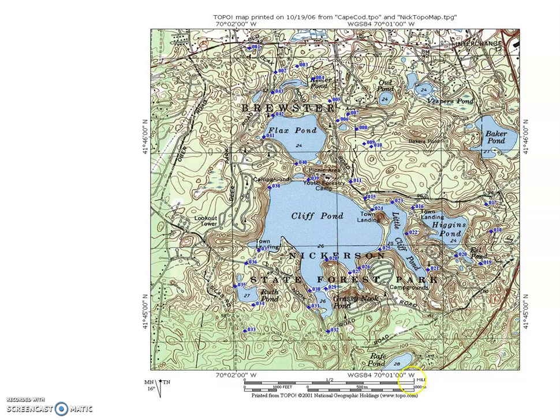So you'll notice that there are 10 sections to this scale. So if this is 0, this is 0.1, 0.2, 0.3, 0.4, 0.5, 0.6, the number we're looking for, 0.7, 0.8, 0.9, and 1 mile. So we were looking for a distance of 0.6. So if you have a ruler or any other type of straight edge, you can measure the distance between here and here. That's your 0.6 miles.